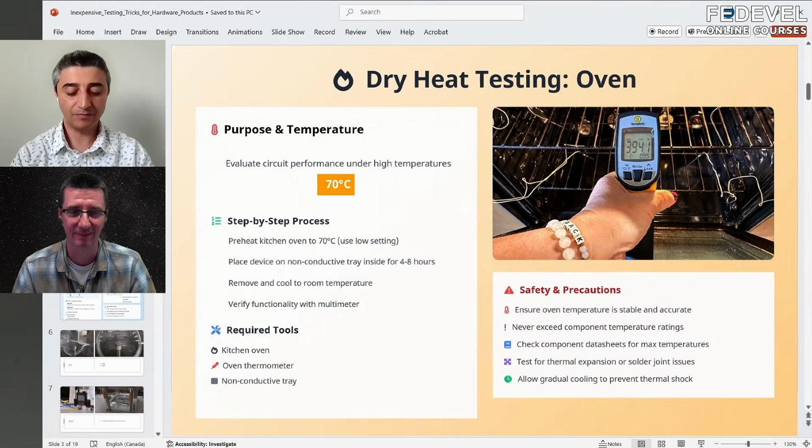Or there are designers who are working on designing heat sinks and cooling systems inside, so they have the flexibility to add these features. But for most IoT sensors that use a battery, what else can you do? You're limited. Maybe the enclosure can be designed a different way, for example the selection of the color, or the place of the processor, where it should be placed on the product. Should it be sitting at the bottom, at the top, behind another component like a sandwich? Making a mechanical change might improve things by maybe 2 to 5 degrees Celsius, and that might be what you need to make sure your design is robust.